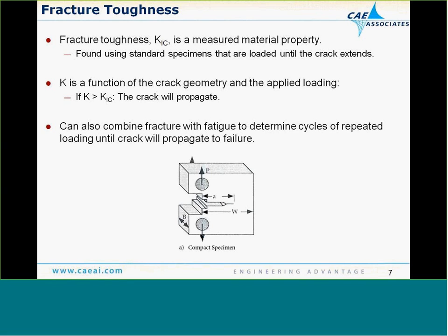Now, what's really of more use is when we combine fracture with fatigue. A lot of times we have cyclic loading, for example, the wind turbine problem I mentioned. In that case, you have a cyclic loading as this thing is spinning, and therefore you can combine fracture with fatigue so that you can calculate how much the crack will propagate for each cycle of loading, and then you can predict at the end how many cycles to failure.